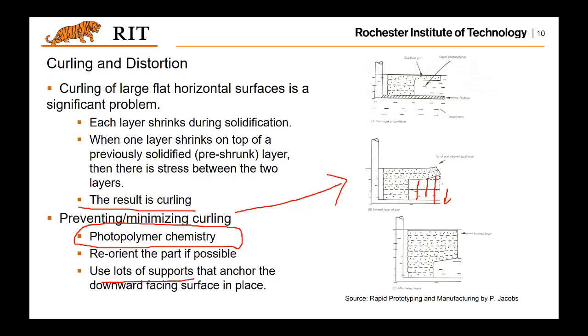But again, if you have more support material, that could cause trouble, especially when you need to post-process those supports. That could also cause surface accuracy problems and feature distortion when you remove the support material. So there's always a trade-off between the amount of support versus the difficulty of post-processing, right? You want to be careful when you decide to add support material.